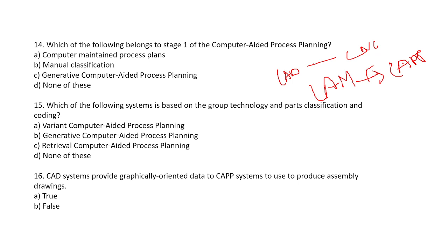So it is based on group technology coding and classification approach to identify a large number of part attributes, or parameters. Then the next stage is generative computer aided process planning. In this stage, process planning decision rules are built into the system itself. And then the next stage is dynamic or generative computer aided